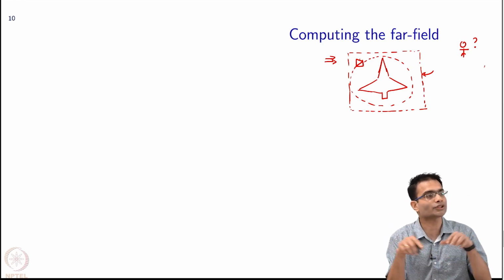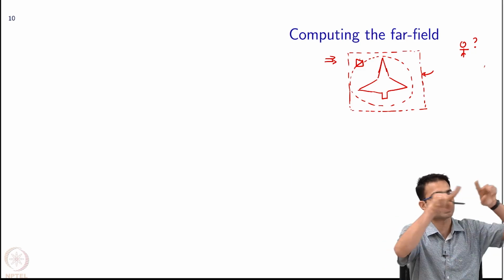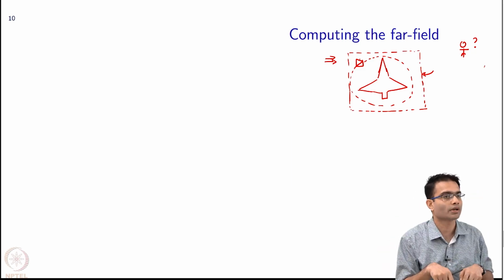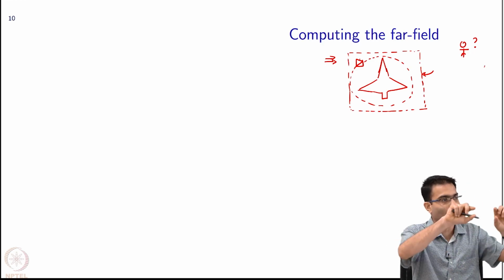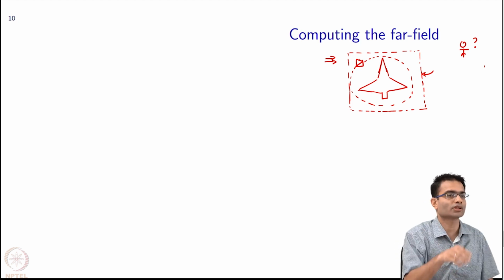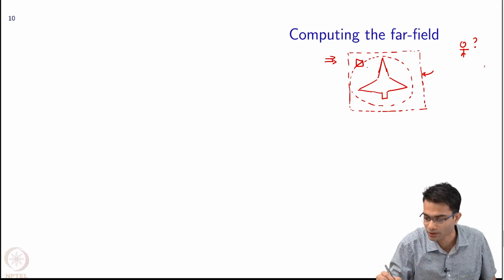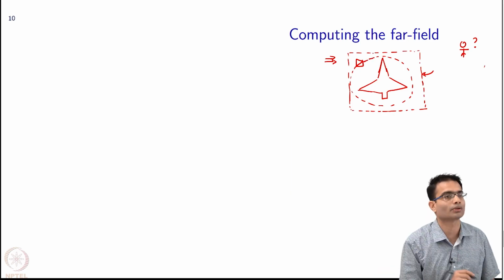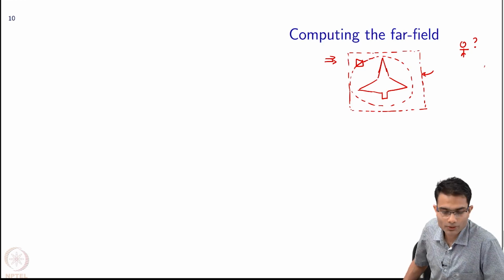When you use your CAD software, you define let's say a circle around it, and the meshing software will respect that edge. It will align the triangles in such a way that you get one nice smooth set of edges. So there will be U1, U15, U25, whatever. Those are the U's that are sitting on this contour. So you now know the field on those points.